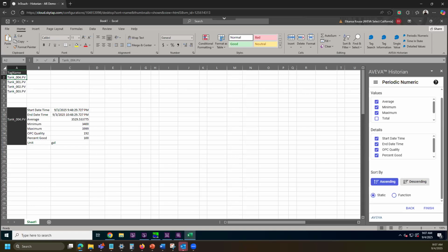Instead of just pulling every raw sample, the historian summarizes the data for you, puts it into statistics such as minimum, maximum, standard deviation, count, etc. These results are returned for an interval you define, for example, hourly or daily. Some of the use cases for this is if you want to create daily production reports, right? So summarizing production counts, averages, or totals per shift or per day.